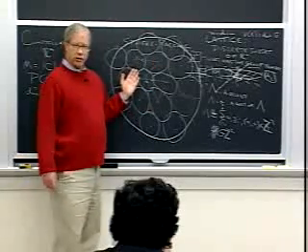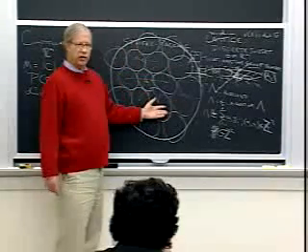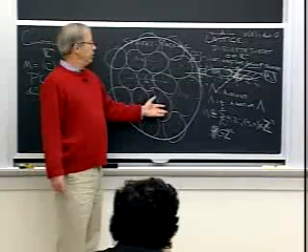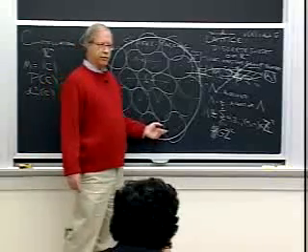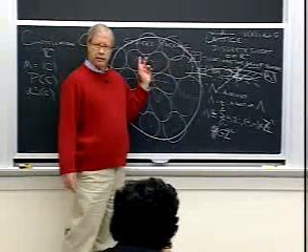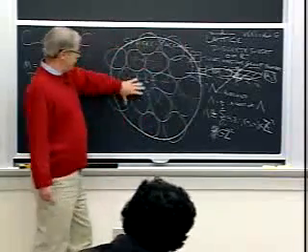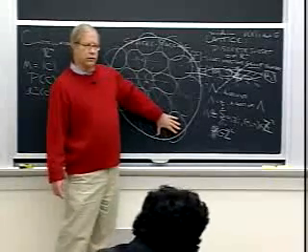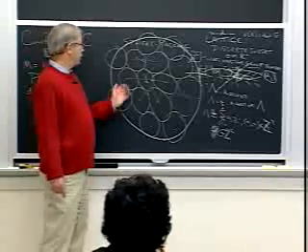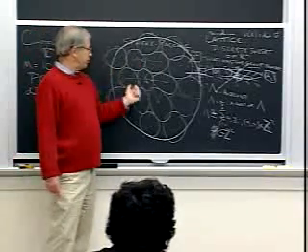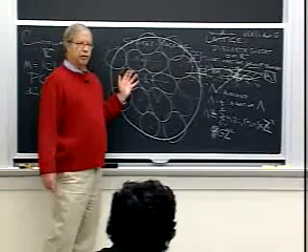But here's the key approximation principle. I'm going to say the average power of this constellation, especially as the constellations get large, is simply going to be approximated as the average energy of a uniform distribution over this bounding region. Suppose I simply put a uniform continuous distribution over this circle, the two-sphere that I've used as my cookie cutter. I'm going to say that's going to be a good approximation to the average energy of these 16 discrete points, which are, by construction, spread uniformly over this region.